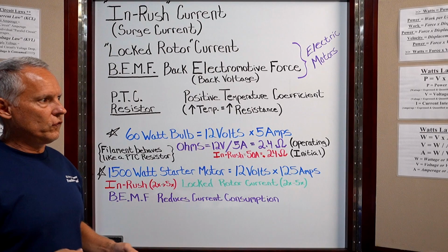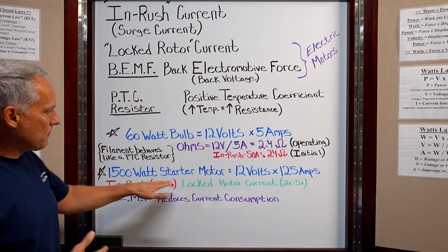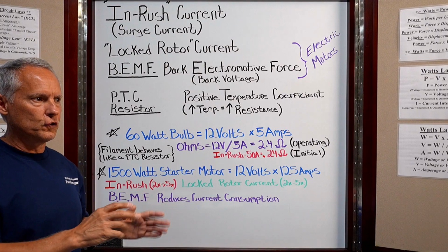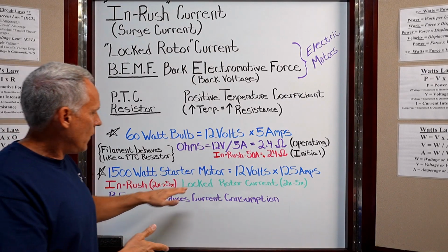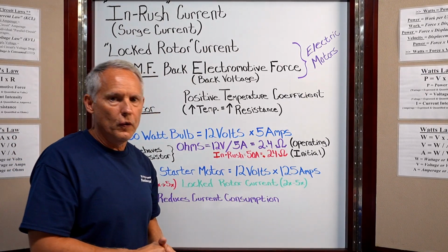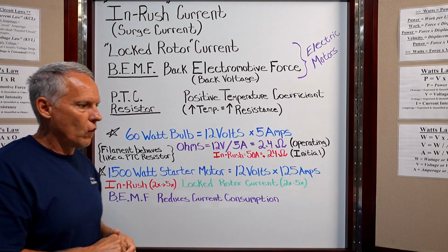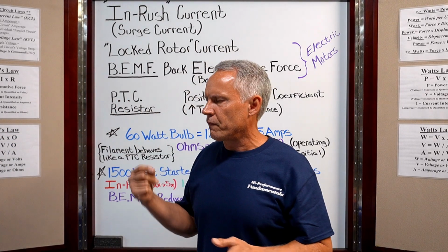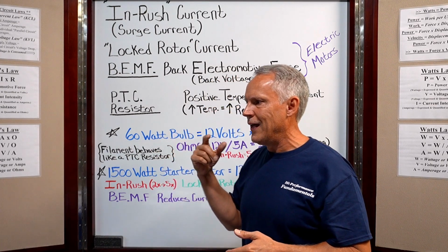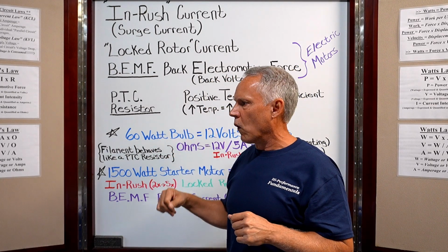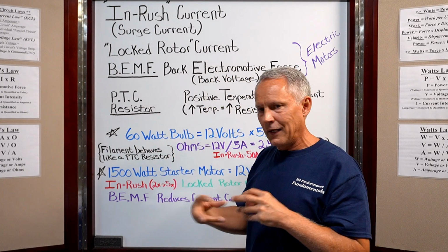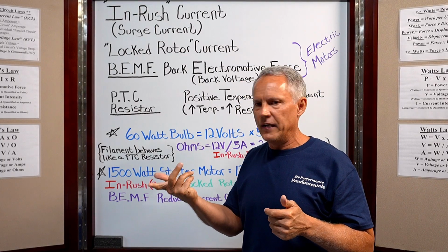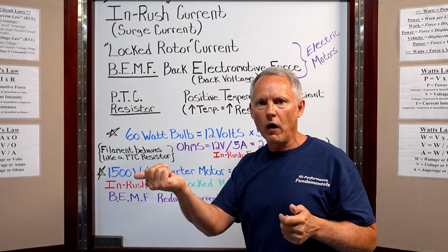Your best bet is you have to know going in roughly where you're going to be. If you're going to design an electrical circuit, you need to know roughly where these calculations are going to fall into. And I think that starter motors are the worst case scenario. And an example of that is this. If you have an engine cooling fan motor or a fuel pump, an electric motor inside an electric fuel pump, you can easily test those. You could bench test those before you ever install them on the car.